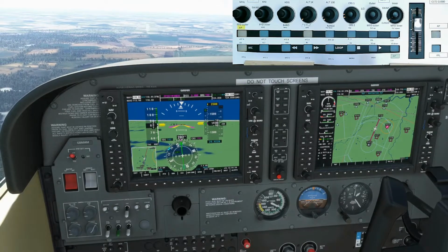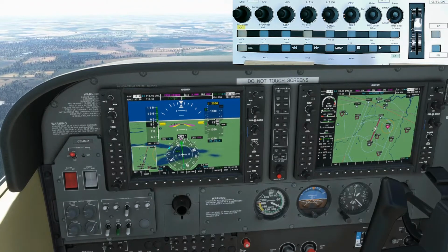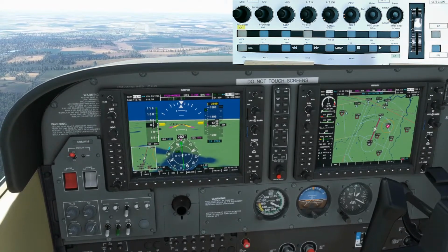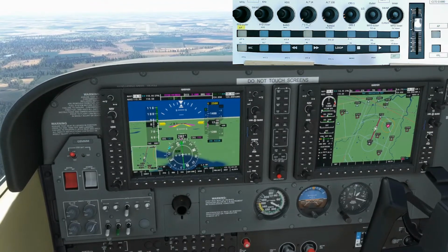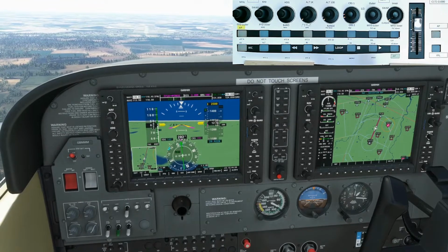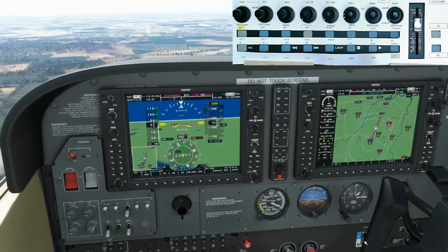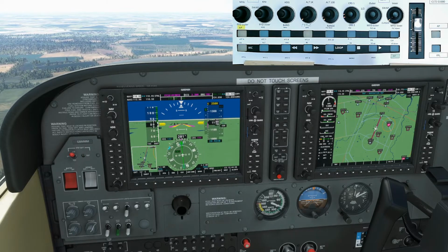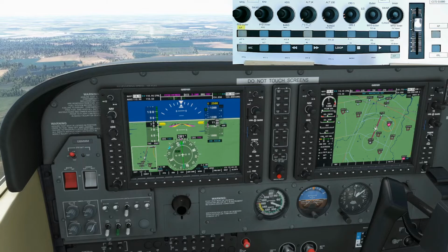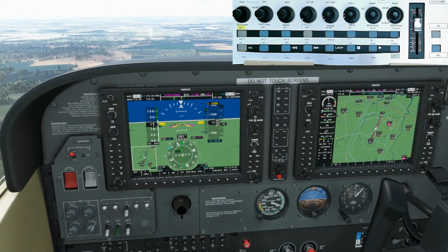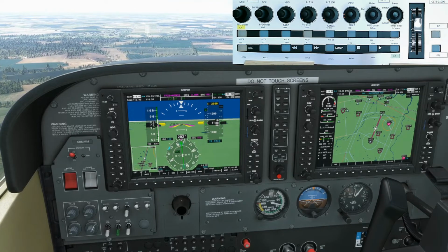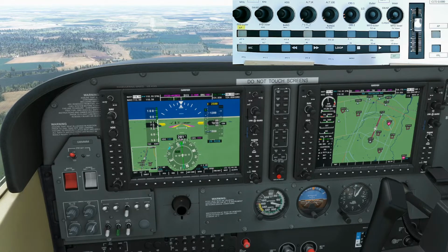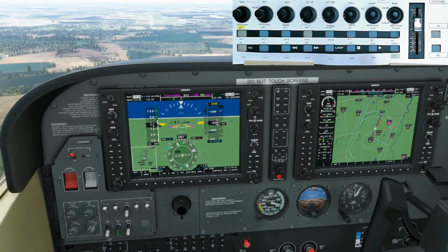Okay, so the speed is in the white area, I could start to bring my flaps in. But as soon as I put the flaps in, I'll get some more drag, so I'll probably have to watch the throttle. Okay, my flaps indicator is down here. And I've gone to the first notch of flaps, which gives you a clearer view of the runway, so it brings the nose down a little bit. And I'm watching that throttle. I'm still on autopilot. And you can see it's swinging us around all over the place. Oh, it's stabilising a bit more now.